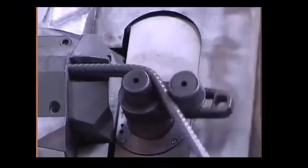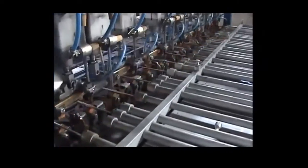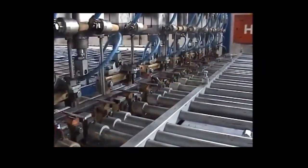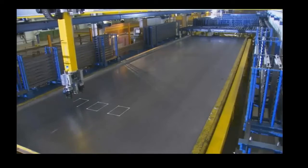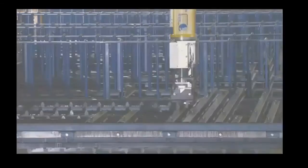With the machine data out of our Revit model, we can provide data for automatically bending the stirrups. Also, a mesh welding machine produces meshes according to our Revit model. A plotter marks the position of the wall openings on the production table.